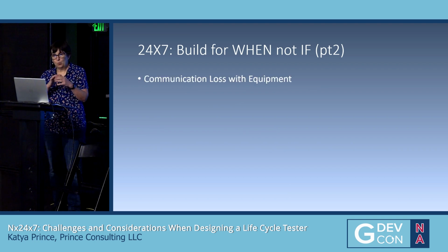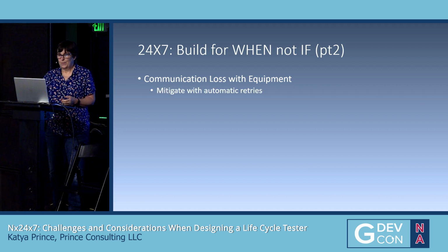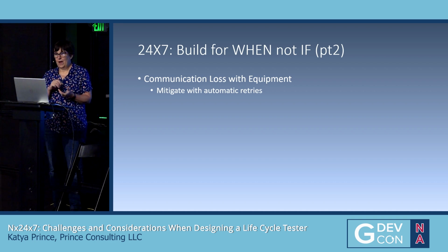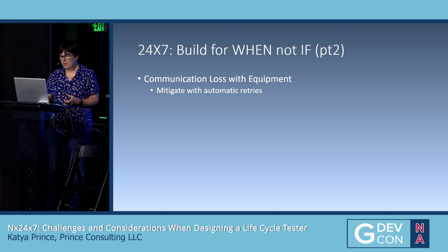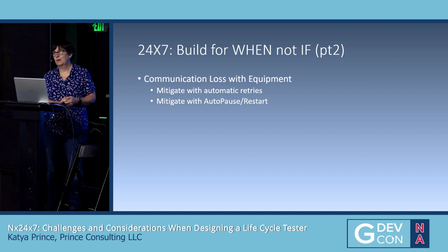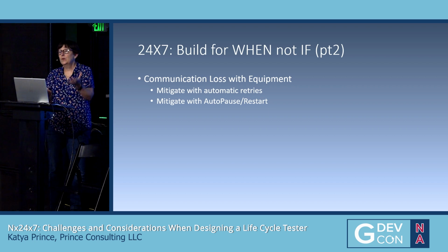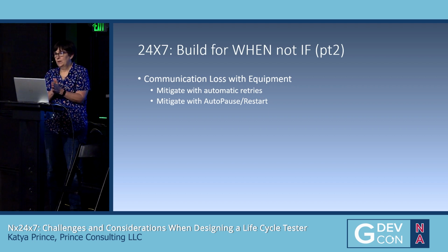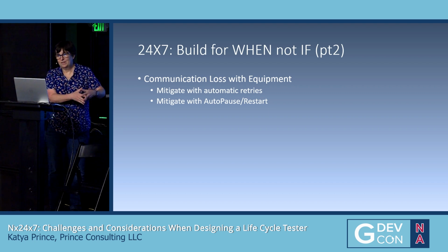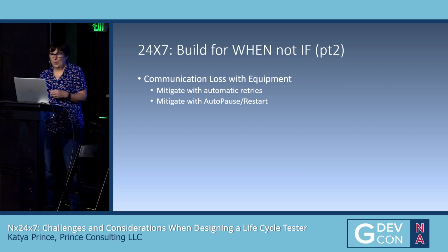The next thing that will happen is you will get communication loss with your external equipment. This is especially true of any sort of power supply or something like that. The way that I mitigate that is to have some automatic retries. Try to talk to it 2 or 3 times before you then go into the safe mode. Again, if you can't talk to it, the reason might be something like the power supply. If your power is lost, you may not have that device on a UPS, you lose communication, you sit and wait, and then once everything comes up again, you restart.